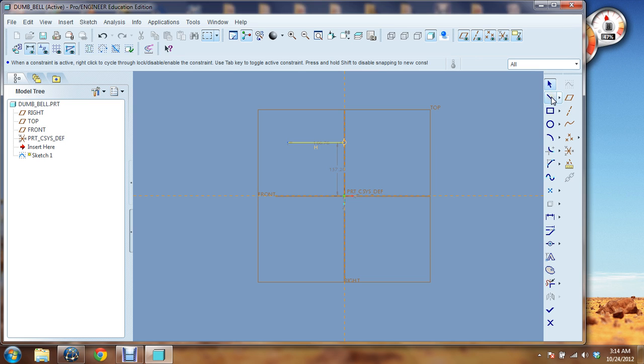So you see up here we have our line again. That's all I'm doing. You can see it's trying to lock to this line again. It'll actually lock to the midpoint. I can lock it to this side, and I can actually lock it to be on that same horizontal line. We can go ahead and do that. We'll just lock it to the horizontal and just bring it off to the side. Actually, let's go ahead and lock it to the reference line. And I'm going to middle mouse click again. So we can go ahead and see all the things that we can manipulate now. We're still not violating any constraints that we placed on it. Constraints being locked on this line, locked on this line, and these two being on the same horizontal line and this being horizontal.